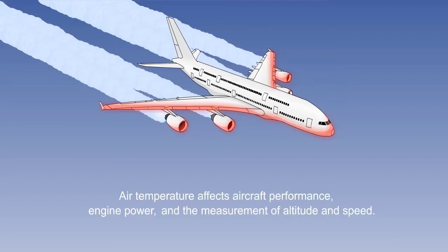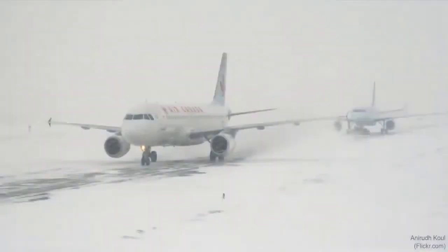These terms are fully explained in the next lesson. This temperature will not be representative of the true outside air temperature. It is the true outside air temperature that we need to know. So in this lesson we are going to look first at the basic types of air temperature thermometers in use and their principles of operation. Next, we will look at a typical total air temperature probe of the type used on modern high-speed aircraft. And finally in this lesson we will consider the errors which the instruments are subject to.